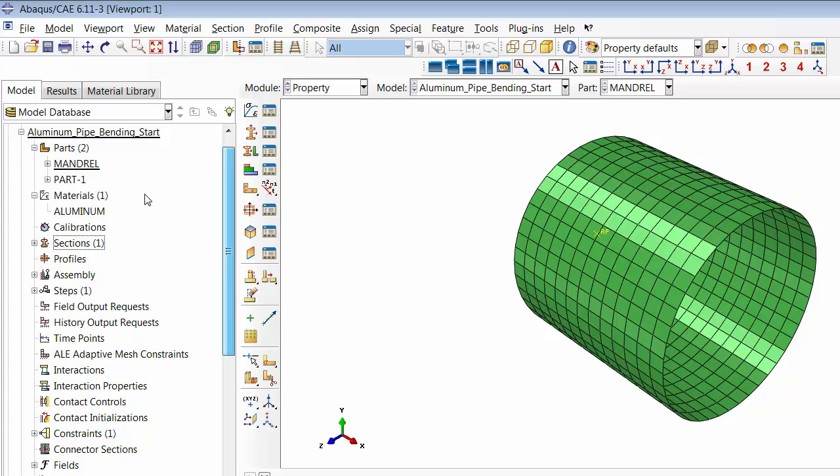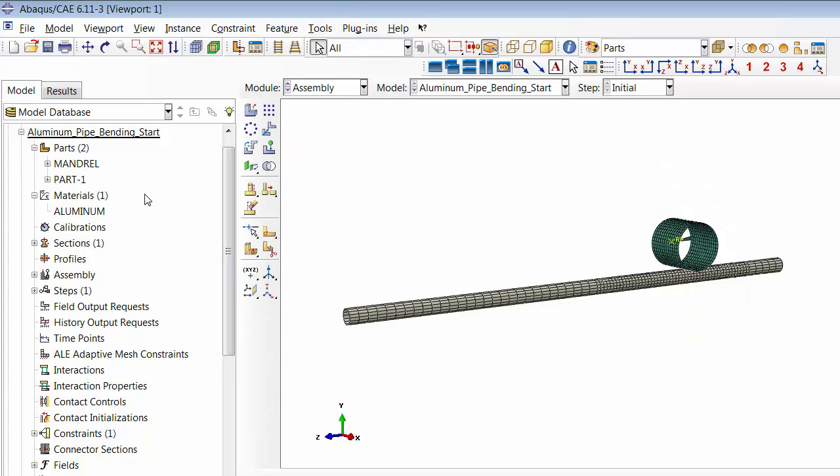Now the important thing. So now we are going to put mainly a surface data. So we'll generate a surface, master versus slave. Now the rigid surface is the obvious choice. It will be a master because it's rigid, and then the deformable will be a slave surface. And the mesh is already meshed in such a way that it is a fine mesh, so that way we may get a converged result out of this.